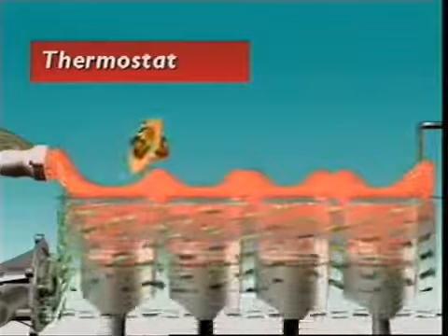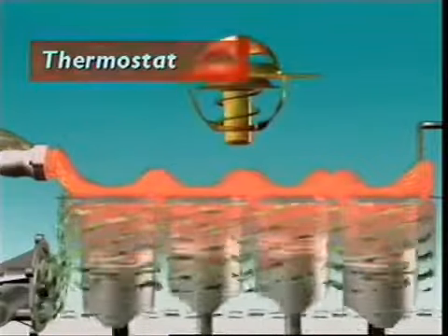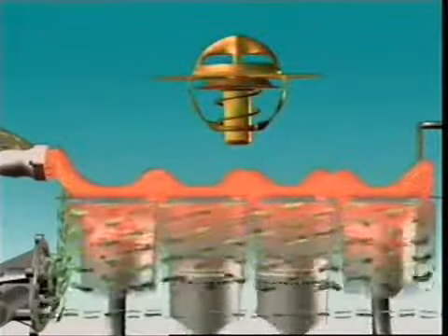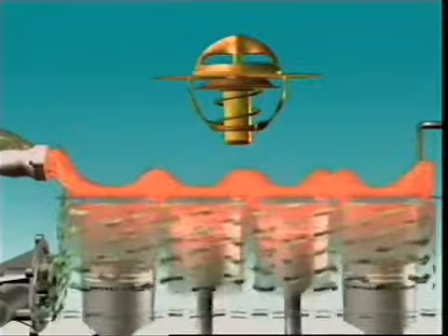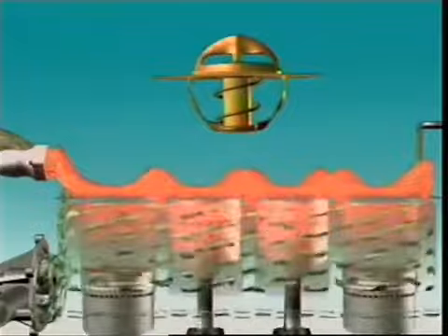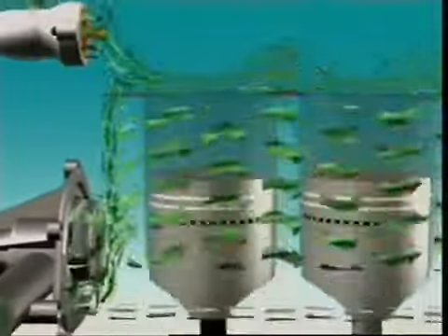The thermostat helps an engine to warm up. It's found in different positions on different engines. It is a valve that operates according to coolant temperature. When coolant is cold, a spring holds the valve closed. When a cold engine starts, coolant circulates within the engine block and cylinder head and through a coolant bypass to the water pump inlet. It can't get to the radiator.